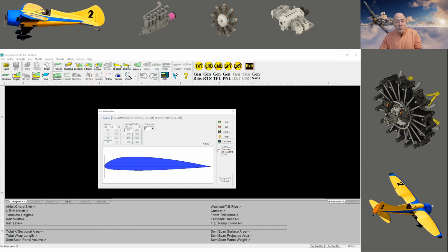And then this is where I get it as semi-symmetrical as I like, but still have a little bit of a rounded bottom. This airfoil is awesome for a plane you're going to be lifting, like a cargo plane. Let's say you're scratch building a Frankenstein plane that you want to carry cargo. This is a great airfoil. It's got a lot of lift. It's got a very round leading edge. It's very forgiving. But there's no math here because this program, honestly, if it looks right, it's going to work